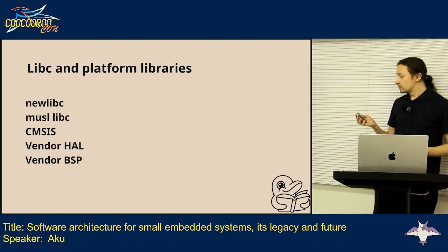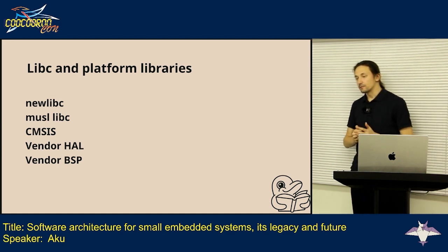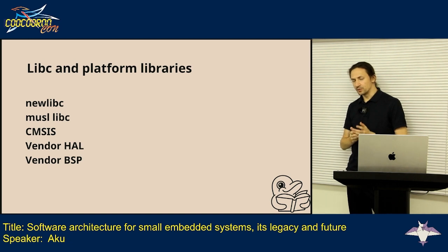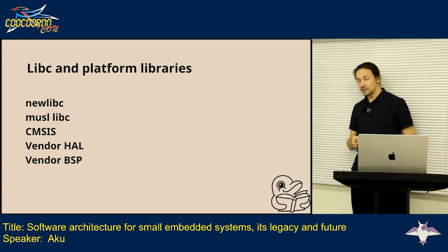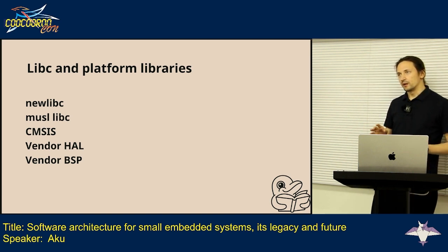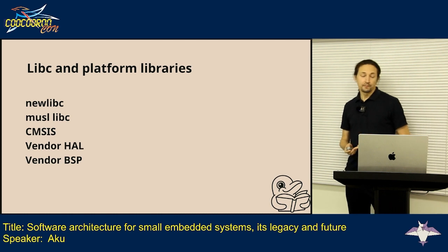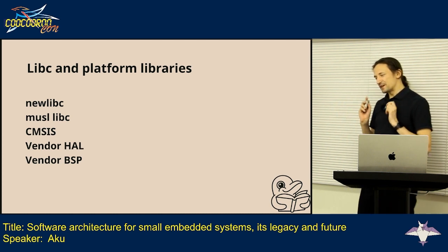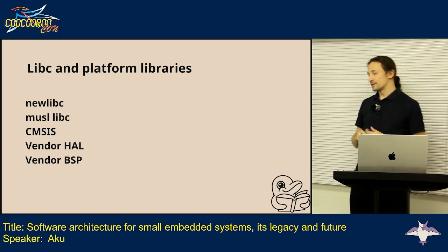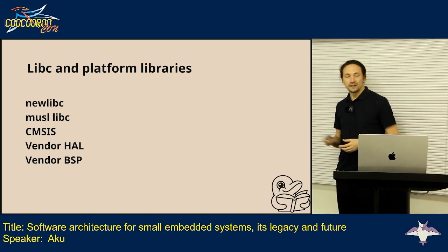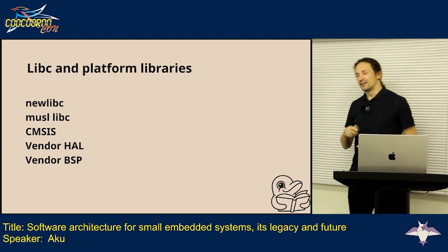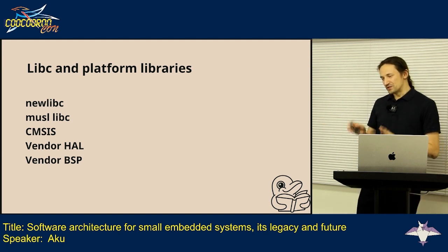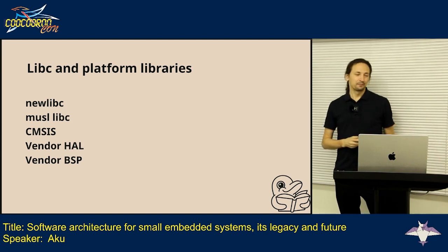That's what we did with Flipper: the toolchain that we designed, the build system, and the glue code that works with libc is kind of trying to make libc usable for microcontrollers. But there are other solutions on the market, and especially if you're willing to pay, IAR can provide you a library that actually was designed for microcontrollers and behaves properly.